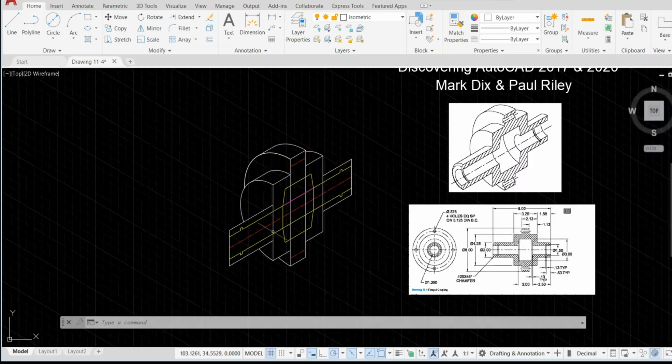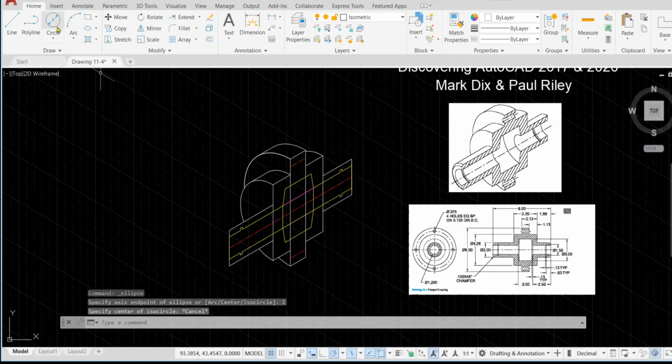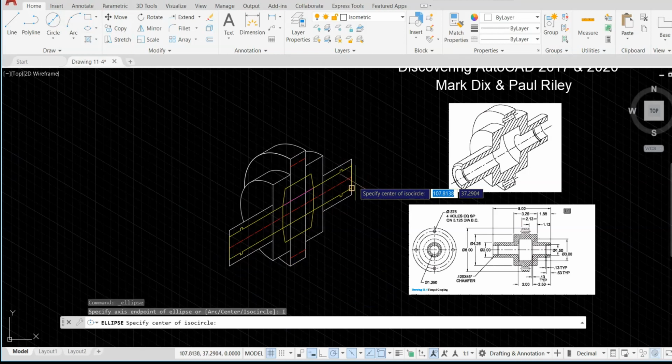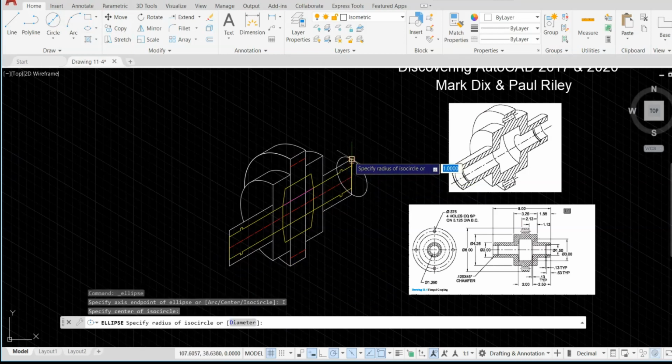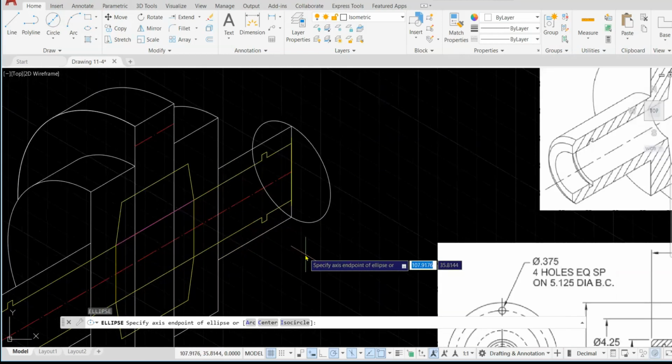Now, after this part is done, and see the rest of the circles down here, we do have other circles from the side, and here 2 circles on top and bottom. So let's do the circles on the sides using the same strategy. Iso circle, and let's do this side because here we need some other chamfer or something. So let's do this circle first. Okay, let's zoom in here, do some trimming.